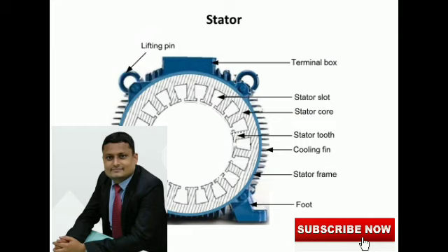Now the guideline says the ratio of slot depth to slot width should be 3 to 5. The width of the slot and tooth at the air gap must be nearly the same. So the slot area equals Hs into Ws equals 548.6 mm square. With Hs by Ws equals 3, Hs equals 40.6 mm and Ws equals 13.5 mm.